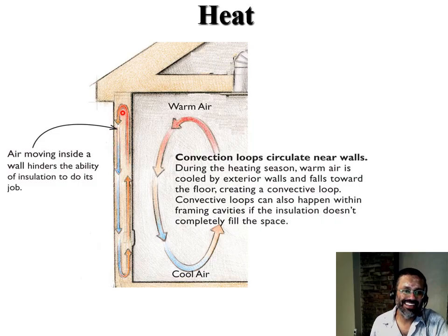So if there's any air and there's not a lot of insulation or no insulation in here, this warm air that's coming into the space by conduction is cooling down and coming down, and as it gets colder, because it's losing its heat to the outside over here because it's colder out here, it wants to sink, and as it sinks, it's losing more heat, constantly going down, getting colder, colder, and colder.